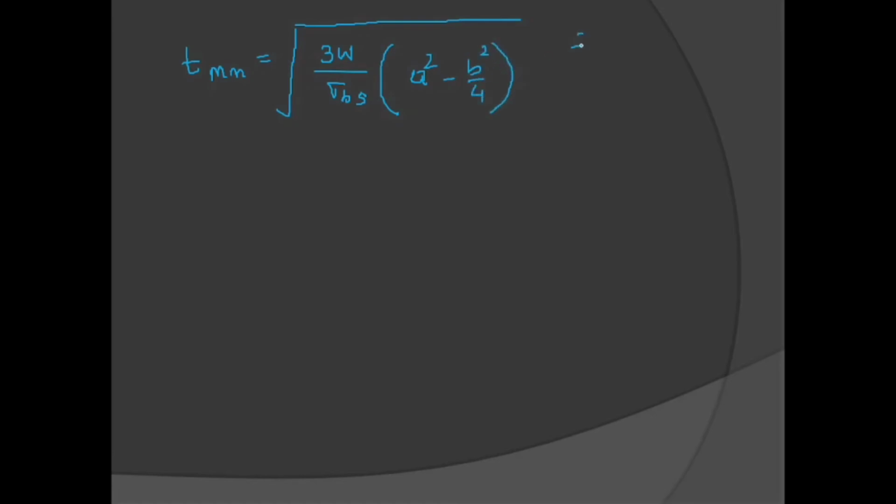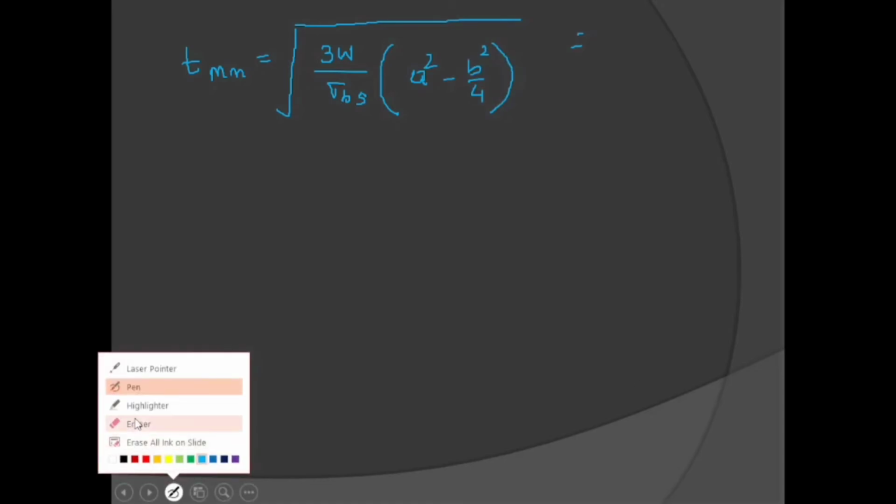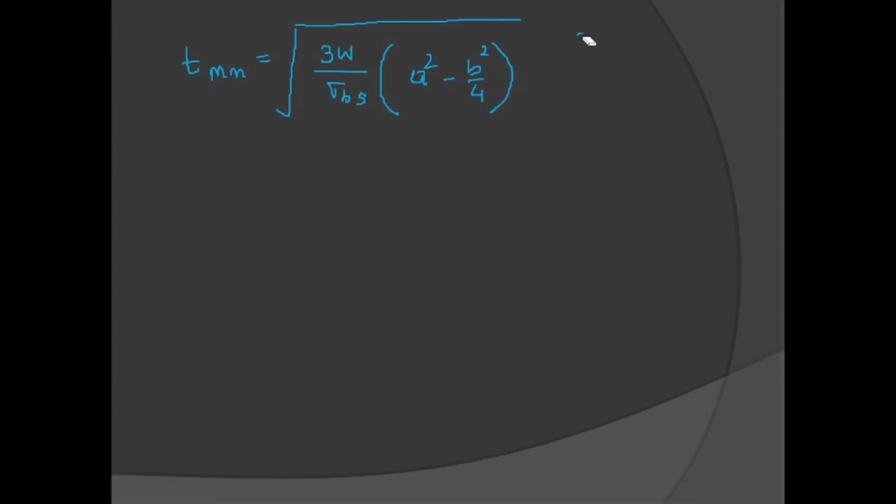Now, what is the net upward soil pressure? That is an important fundamental. Net upward soil pressure is a very important condition. Here W is not given, but the net upward soil pressure is in general calculated. W is calculated separately. What is the load? Load is 750 into 10 to the power 3 whole divided by the area of the base plate that is provided, and the base plate is provided as 600 by 350 size.